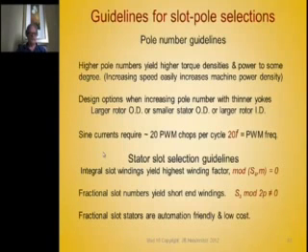Well, if you double the number of poles, the yoke or the back iron is cut in half. So what that means is, if you use a thinner cross section in the yoke of a stator, there are a couple of things you could do with that. You can keep the stator OD the same, and make the slot depth the same in the stator, and make the rotor larger. Or your other choice is, whatever you reduce the thickness of the yoke by increasing the number of poles, you take that off of the OD, and so you make the OD of the motor smaller. It depends which is the most important.